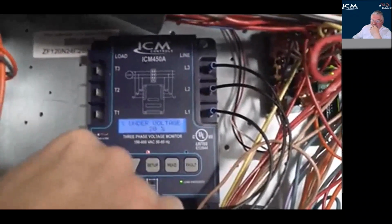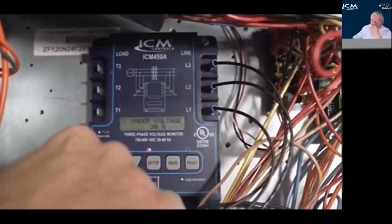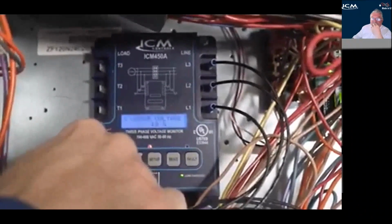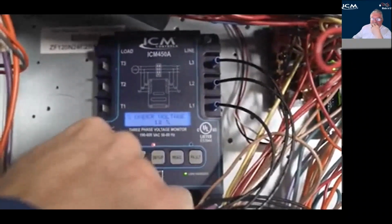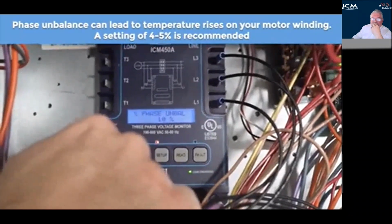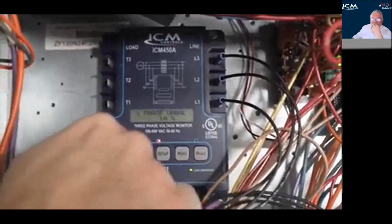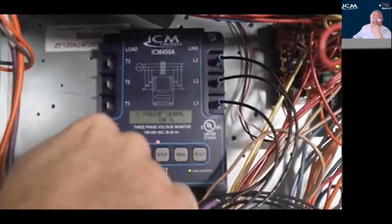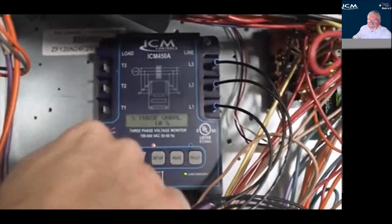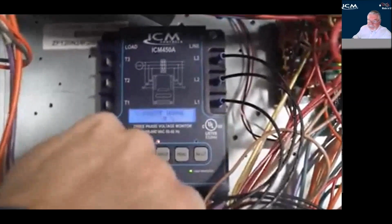Under voltage, same idea. You can adjust the percentage of under voltage allowed before the unit protects itself. Next is your phase unbalance. So that's the 10% as it's monitoring the difference between the three different lines as to what's an allowable, out of range. So we'll get that to about 5%.